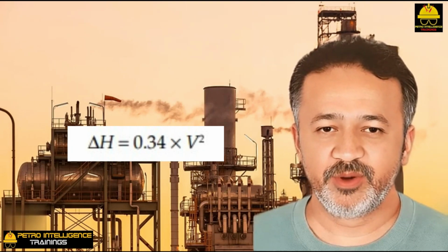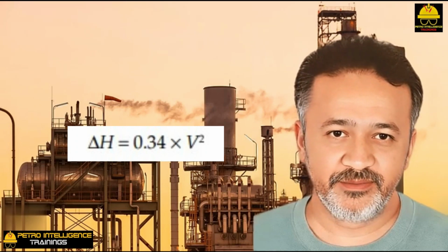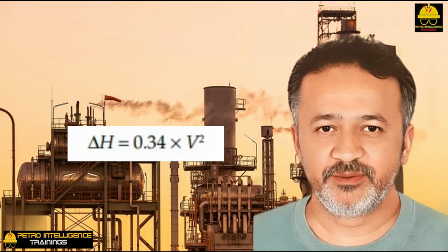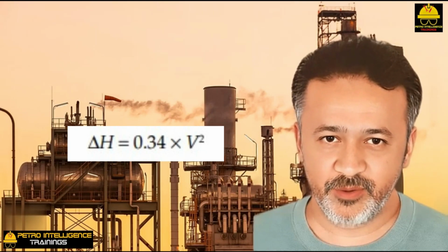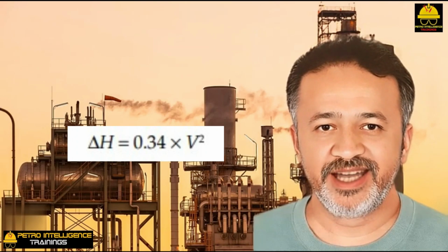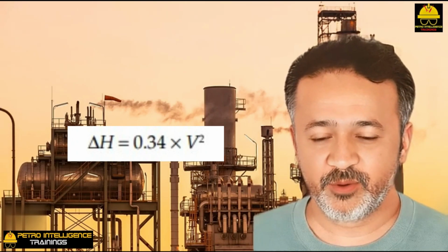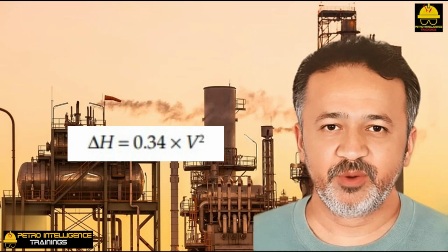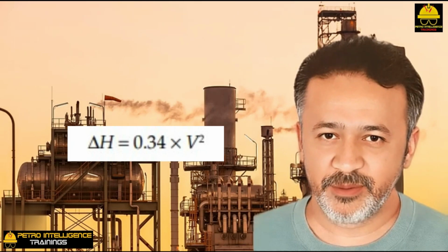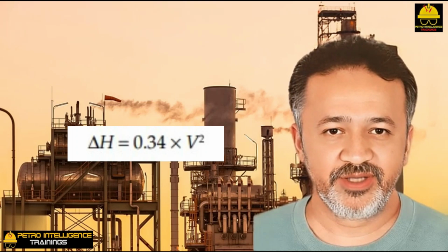The energy to accelerate the fluid in the draw-off nozzle comes from the potential energy of the fluid. This is Newton's second law of motion. The coefficient used in the equation above, 0.34, assumes the process fluid has a low viscosity. For most process nozzles, this is a reasonable assumption. Detailed information on draw-off nozzle coefficients has been published in Crane, Flow of Fluids Through Valves, Fittings, and Pipe, technical paper. For me, I don't trust published coefficients.